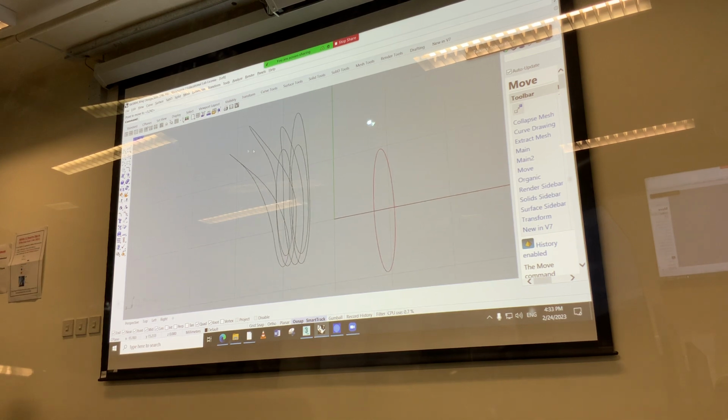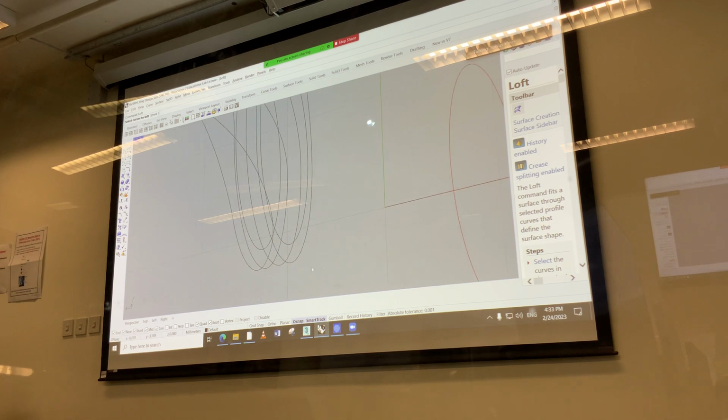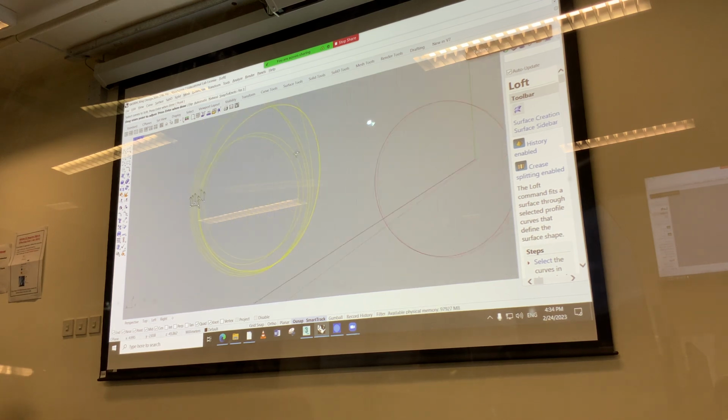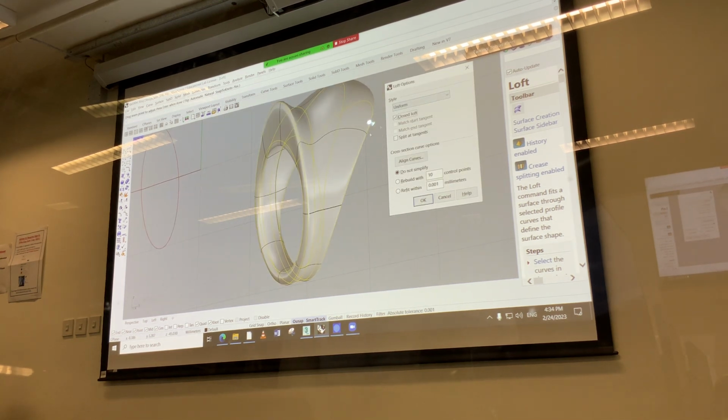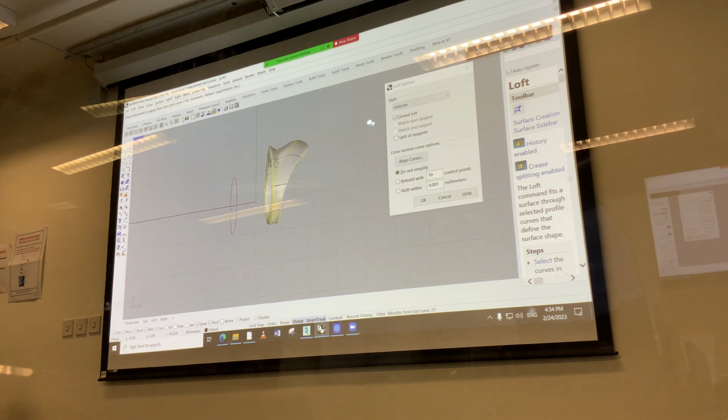So now this is getting quite interesting. So the curve of this loft will now have to go from the inner to the outer, to outer 1, outer 2, outer 3, outer 4, inner 2. The seam curve is correct. Uniform, close. Interesting, huh? Now we're getting actually a really interesting profile ring already.